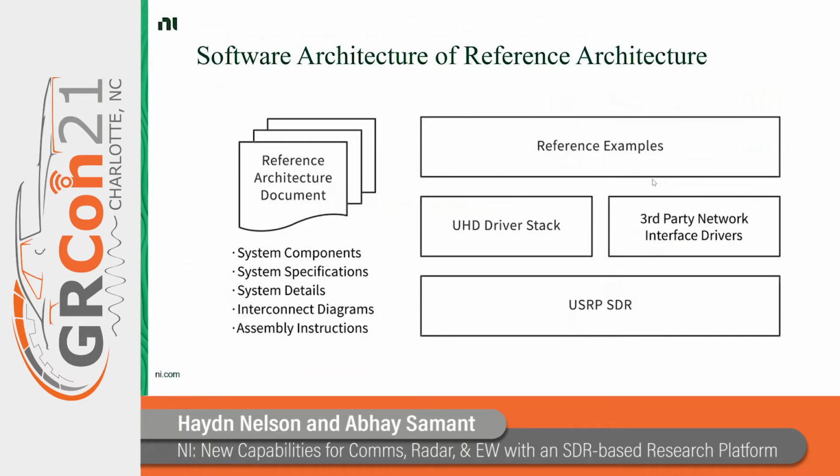Let's look at the software architecture of the reference architecture. It's built on the UHD driver. The operating system that it is built on is Ubuntu 20.04. We have tested with both the UHD 4.0 release and also the 4.1 release. On top of that, we are using third-party network interface drivers. We have tested the reference architecture with the Intel X410 and the E810 network interface cards, and also with the Mellanox network interface cards. And then the reference examples that we are providing are built on top of that.